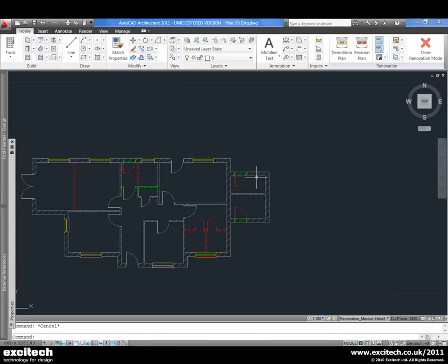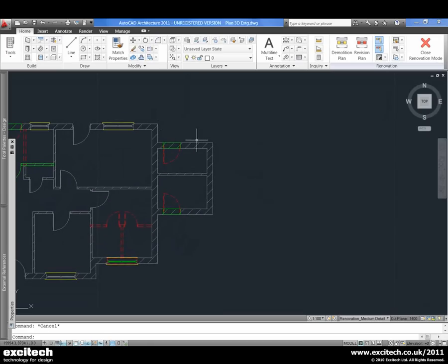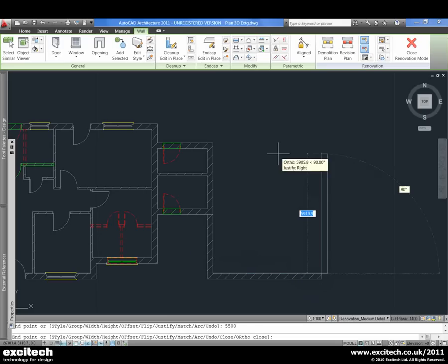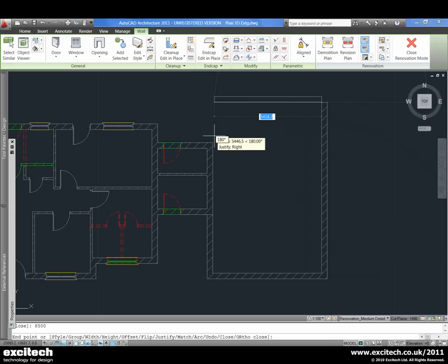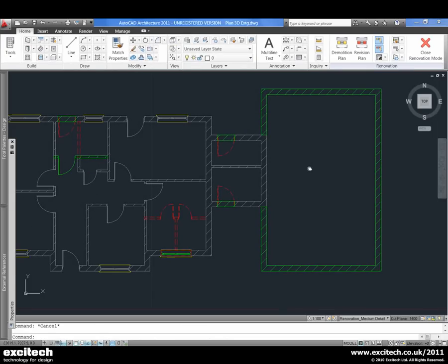And we're also going to add an extension on to the side of this here. We're going to build them a new garage, so we can take a bit of our existing wall here and just say add selected again, and then start to draw our walls around. We can use our dynamic input so we can see how quickly we can start to generate some of these plans in here. So once that's finished, it'll go straight away into a proposed wall style.